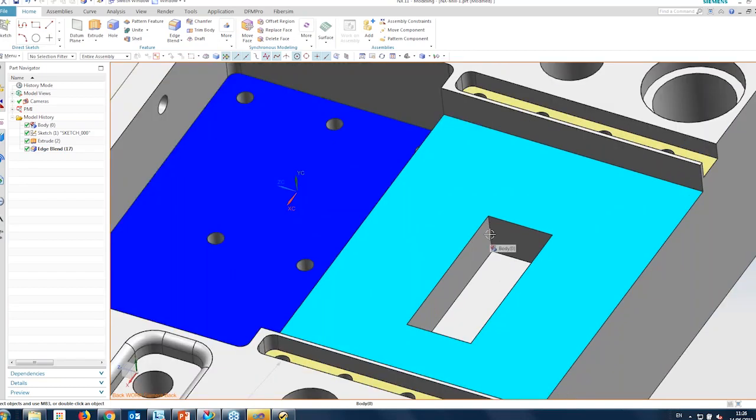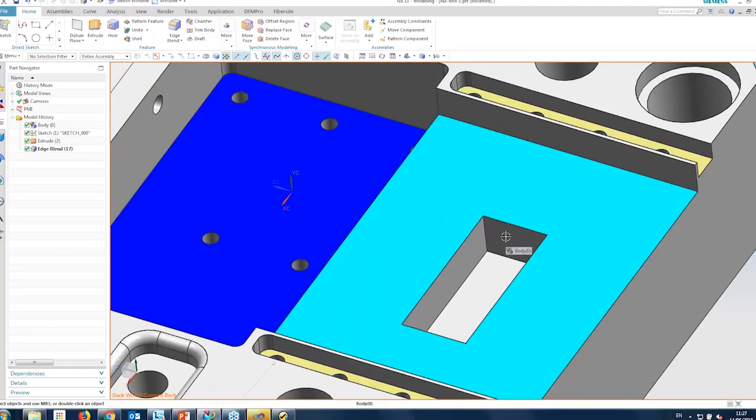So I'm just going in here, adding a certain amount of radii to all these specific areas, and what I'm getting is a framework or an opportunity to improve my design quickly to eliminate these sharp corners. So I am quickly eliminating all the sharp corners on this particular pocket with a value that has been specified in that area. I've eliminated the sharp corners, and now I say okay. So I've added the fillet radii at the end.